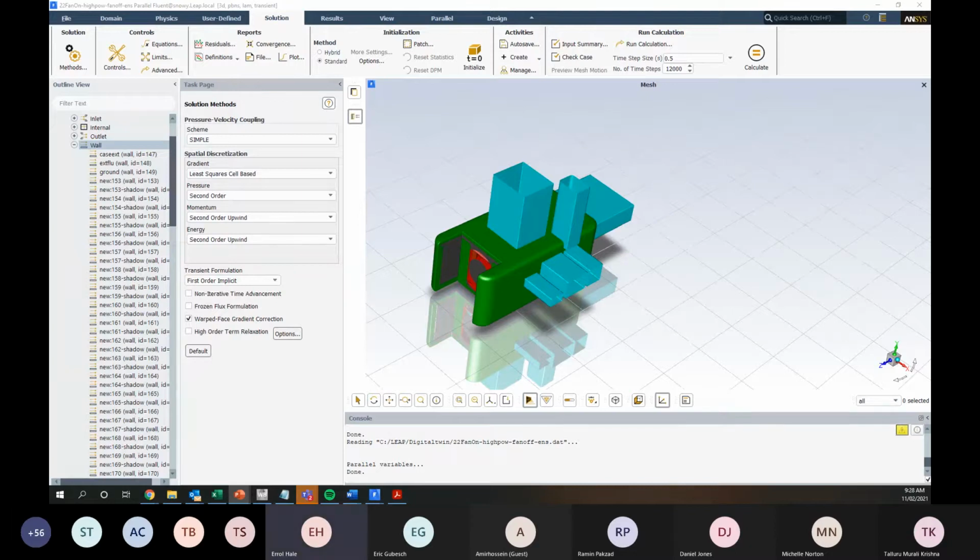Okay, let me just check for questions. So the question: I don't understand how the pressure-based solver can work for flows up to Mach 3. The flow chart of solver equations you just showed implies otherwise. Oh, I'm not sure what flow chart we're talking about, but the pressure-based solver does work up to Mach 3. The pressure-based solver does still include density. It's just based on pressure. So the density-based solver is solving based on density, but they can both include compressibility effects due to a changing density.